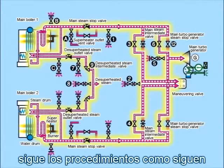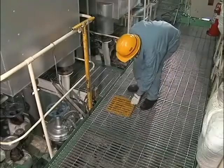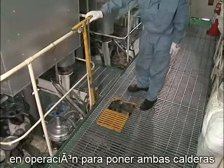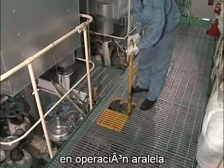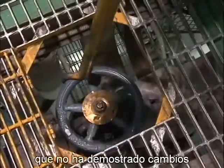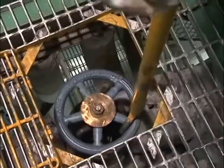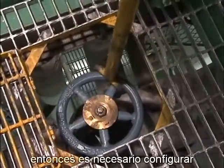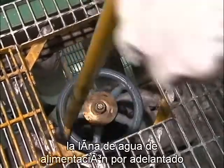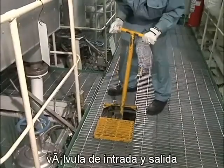Key points of the procedures are as follows. With operation to put both main boilers into parallel operation, the layup boiler water level, which has shown virtually no change, begins to drop as steam is supplied. Therefore, it's necessary to set up a feed water line in advance by opening the feed water control valve's inlet-outlet valves.